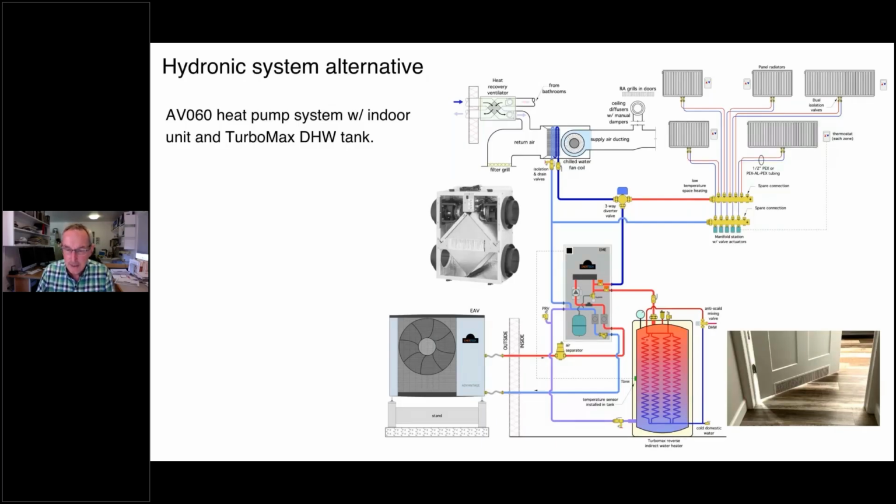And the space conditioning outlet pipe here goes up to a 3-way diverter valve. This could be a valve that's operated by a 24-volt signal. Basically, it takes the upgoing flow here, and I'm showing it in a blue line. So let's say we're in cooling mode. In cooling mode, it's going to divert that chilled fluid up through the coil of an air handler. And then the fluid, as it absorbs heat, comes back into the indoor unit.